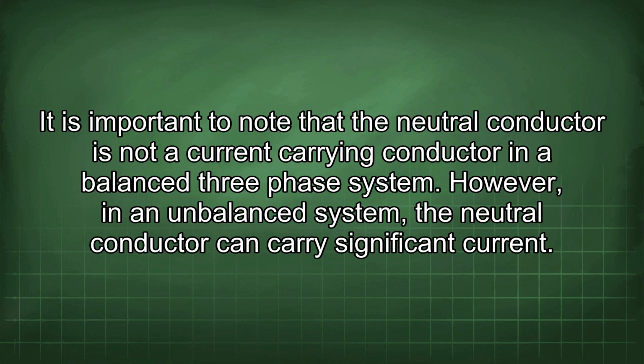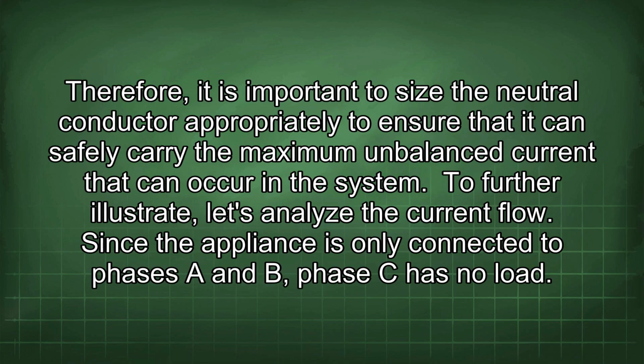It is important to note that the neutral conductor is not a current-carrying conductor in a balanced three-phase system. However, in an unbalanced system, the neutral conductor can carry significant current. Therefore, it is important to size the neutral conductor appropriately to ensure that it can safely carry the maximum unbalanced current that can occur in the system.